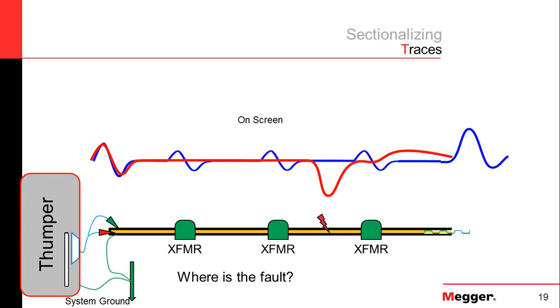It's not going to cause any problem. We don't recommend that you use the thumper in the cycle mode going through transformers. There's no reason to do that either. If you're actually trying to put paint on the ground to say this is exactly where I want to dig up and put a splice in, you can always do it on the isolated cable.